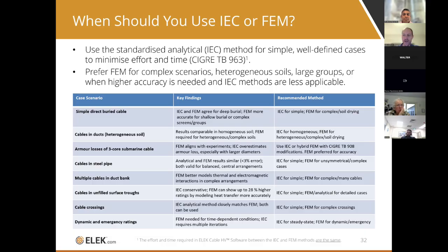But if you're an owner of these assets and you're worried about longevity, you might want to be more conservative, or I would say FEM is more accurate. But you're not strictly mandated to use FEM. That's down to your own engineering judgment.